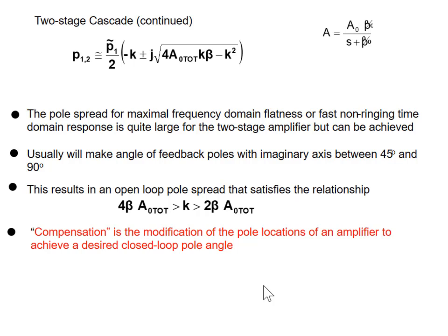I was going to have another slide and I ran out of time before this lecture. There are some op amps that are sold that are called decompensated op amps. You look on the data sheet and it says this op amp is only stable for closed loop gains bigger than 10. That means don't buy that op amp and put it in unity gain configuration.